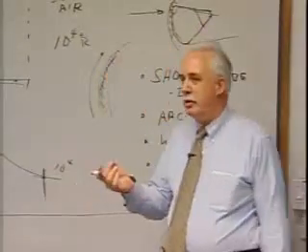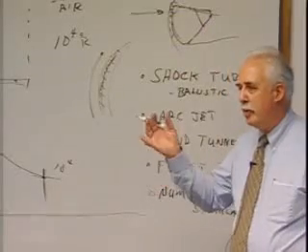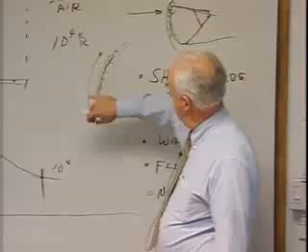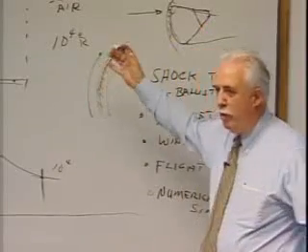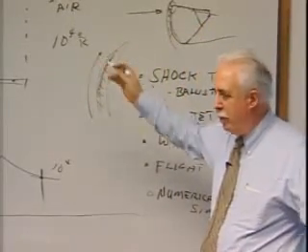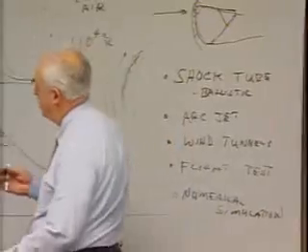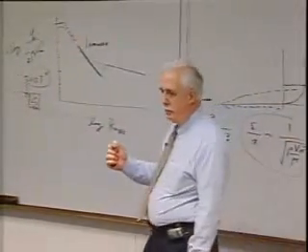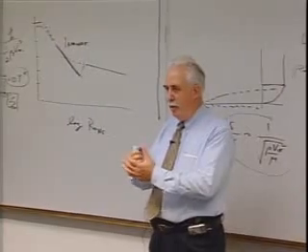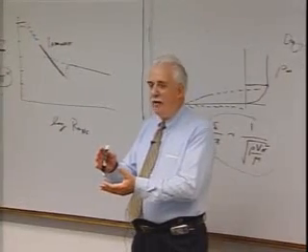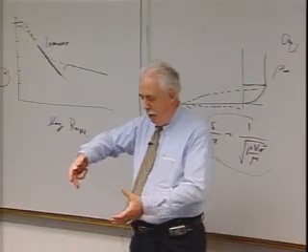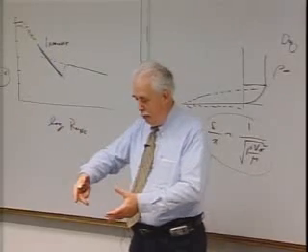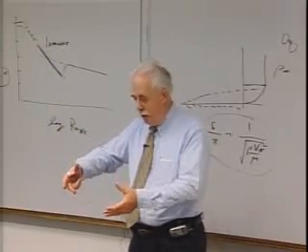The honeycomb wasn't as high temperature as the carbon. Okay, that was just there to hold it as a system degraded. So the combination of the two-dimensional flow, which we really hadn't simulated on the ground, all we could do is in the arc jet, basically little pucks to test the ablator. Okay, you're dealing with an awful lot of energy, and if you spread that energy over a large surface, the enthalpy basically goes down. The heating on the surface goes down.